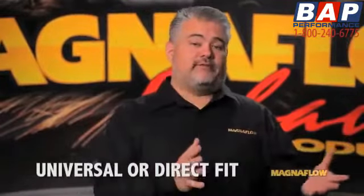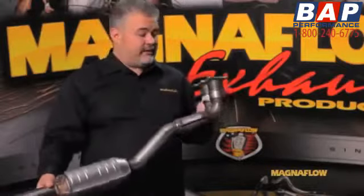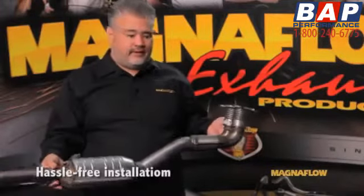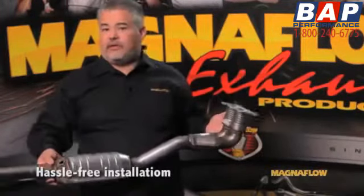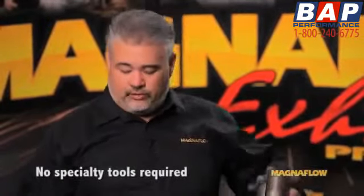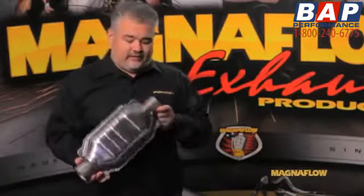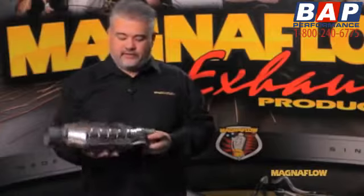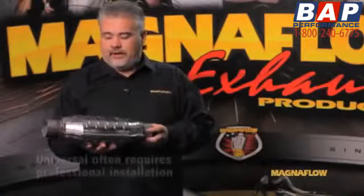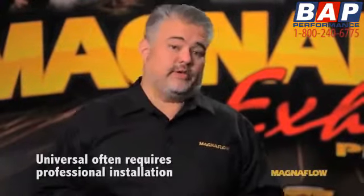The first thing we need to determine is what exactly does that customer need? We have a direct fit and a universal. A direct fit, as you can see in the product in my hand, has an interface on either end and, like the name implies, is made to fit directly into the vehicle. It requires little fabrication, if none, and also basic hand tools. A universal, on the other hand, as you can see, has a pretty much straight-through design. You're going to have to do some degree of pipe fabrication, articulation, cutting and welding might be required, but ultimately it's something that the average user may not have the capacity to do, and we want to make sure the consumer knows this before taking home the product.